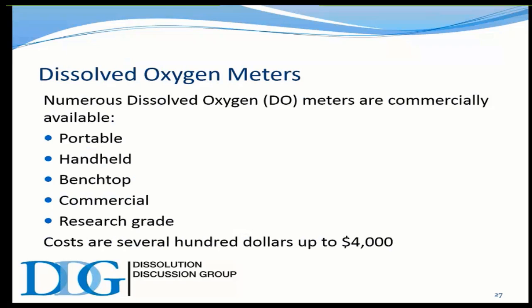The technology of dissolved gas meters has gotten so much better over the years that benchtop models were usually used, and they were thousands of dollars a piece. But now there's a lot more portable handheld units that may be used. The accuracy and precision may not be as great, but accuracy in the 1/10 of a part per million range would be helpful.